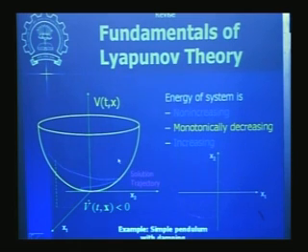So there is a strong correlation between the energy based or Lyapunov function, some positive definite function, and its derivative, the properties of this positive definite function and its derivative, and the stability of the system. This is the basic fundamental understanding of Lyapunov theory. Do you see that? It is important to understand this point. Once you understand this, then the theorems that Lyapunov has presented are apparently clear.